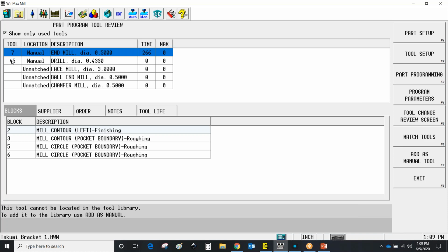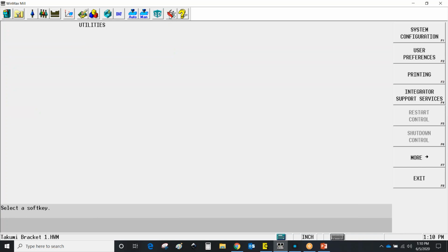So that's how the matching works. We can turn it on, which has some benefit, but can also be a little problematic. Again, my two different types of end mill example. Or we can turn it off where it puts a little bit more pressure on the operator to select things. However, it gives you more control over what it's picking. So you're literally picking these tools for it. So that's pretty much the settings that we need to talk about on the library side.